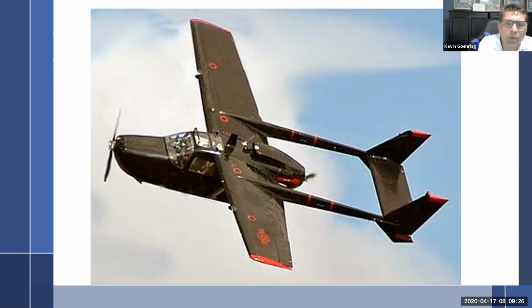So there became an airworthiness directive that you actually had to lead off with your rear engine. Everybody wants to be cool and take both throttles at the same time and mash them forward. Well, this plane, you have to actually bring the rear throttle up first and get a positive indication of roll before you can bring the front engine on.